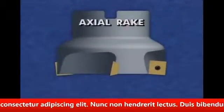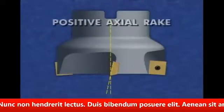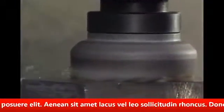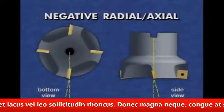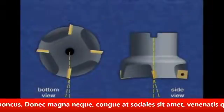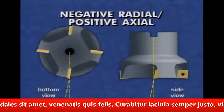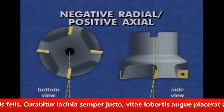The axial rake is the angle measured between the insert face and an axial line or plane, and it may also be positive or negative. The combination of axial and radial rake angles yields three geometries of milling cutters: negative radial and axial, which offers the strongest edges but generates the greatest cutting forces; positive radial and axial, which provides the freest cutting; and negative radial, positive axial, which presents a strong edge to the work but pulls the chip up.